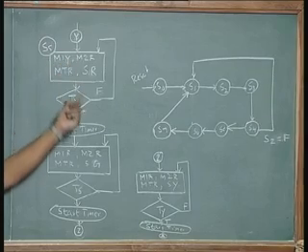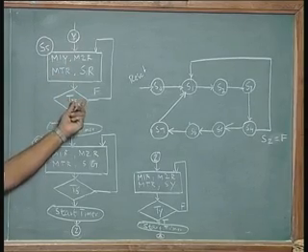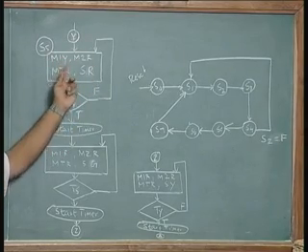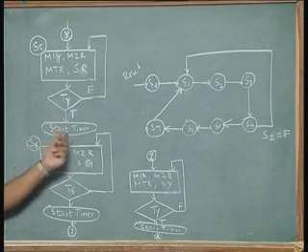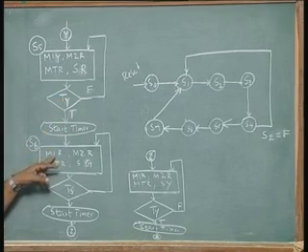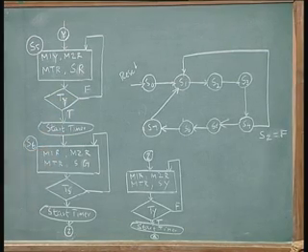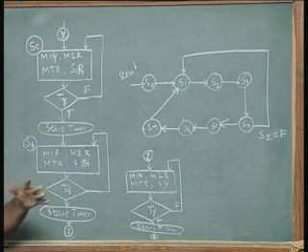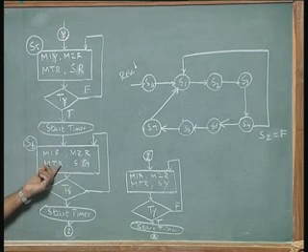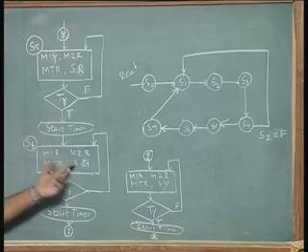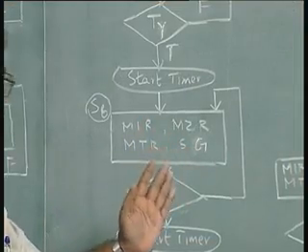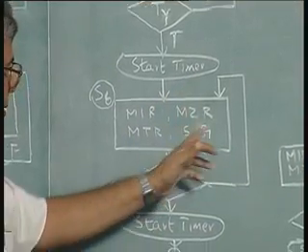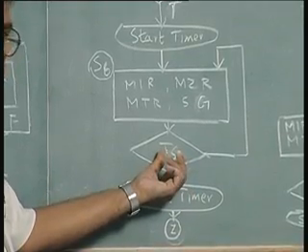So, yellow duration is monitored, until the yellow duration is over, the main one remains yellow, after the duration you start the timer again, main road becomes red from left to right, it is already red right to left, that means both the sides the main road traffic is blocked, turn from main to side is also blocked, then the side road is free to turn from side road to main road, become green, the duration of that is Ts,